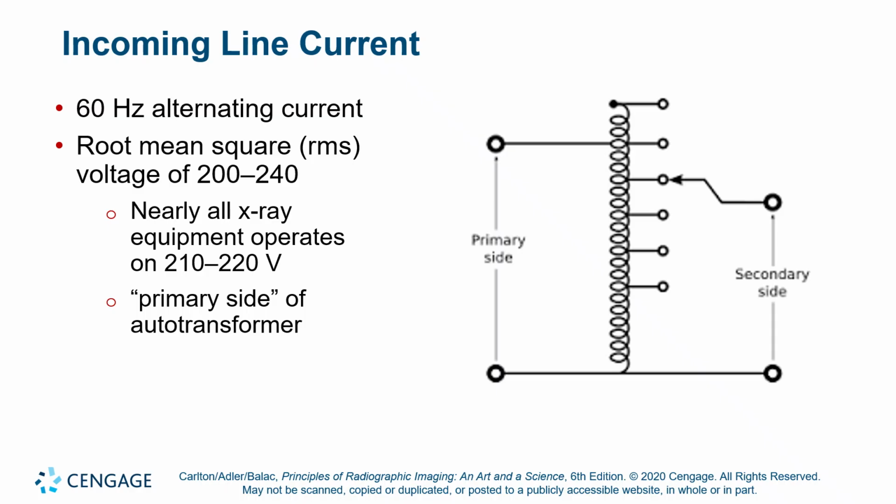What the line compensator does is it's another voltmeter measuring the incoming voltage and then selecting a proportional number of coils on the incoming side of the auto transformer. So if it's 240 volts coming in, then it's got a switch that includes 240 coils. And then you get the trick that I explained last time where the denominators of the transformer law disappear and it's just number of turns secondary equals voltage secondary.